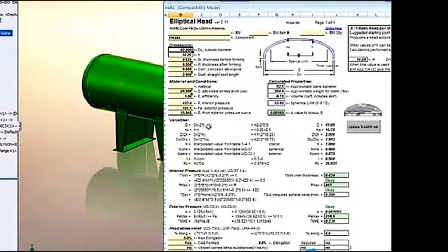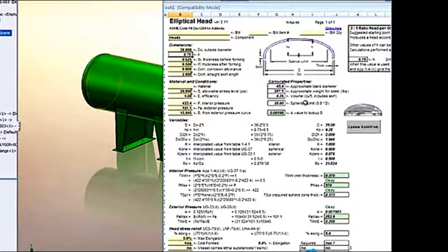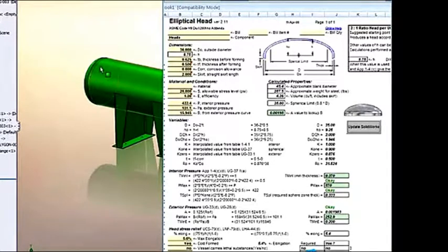What we want to do is change the outside diameter of our tank from 42 to 36. You can see all the dimensional values that update. Even the check says whether or not it's okay. Now that we have some new dimensions, how do we get all these dimensions back into SOLIDWORKS to control our design? Well, we're going to do that by using a macro. This macro is actually embedded inside of SOLIDWORKS, so as I click that button, watch the geometry on the screen, it actually updates. So we have some macro information inside of an Excel spreadsheet that's controlling our SOLIDWORKS geometry.